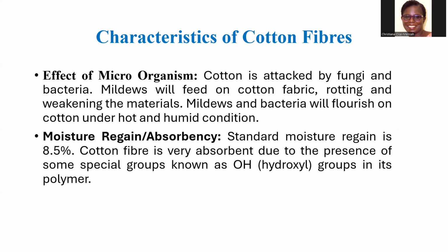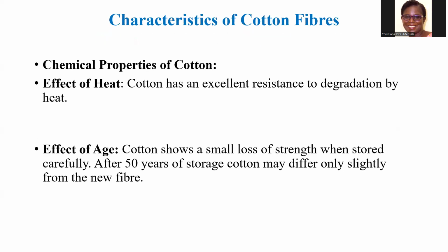Effect of microorganisms. Cotton is attacked by fungi and bacteria. Mildews will feed on cotton fabric, rotting and weakening the materials. So mildews and bacteria will flourish on cotton under hot and humid conditions. When you put it in a very hot place, it can produce mildew because it produces something like perspiration, right?